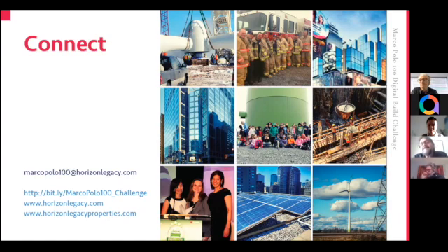Yeah, I would think, with any non-conventional building material, and if this is a membrane structure, an inflatable structure, because a tall building will require it to be non-combustible, it's really important that whatever this is made out of is non-combustible, and that's covered in the code. And we may need to look at, sometimes you have to get materials tested in Canada if they aren't already classified through the Canadian standards, CSA.